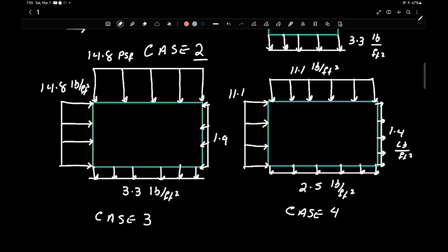This will conclude this lecture, and of course the one thing you have to remember is kind of important. Put this in Excel, and when you do that, you have to do a comparison of the design tornado and wind pressure for a windward and a leeward wall over the height of the building. And for negative internal pressure in the north-south direction, also positive direction, you compare both of them. And again, the ASCE load combination requires these things.